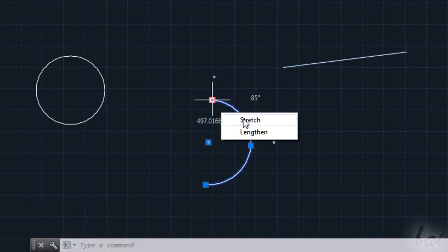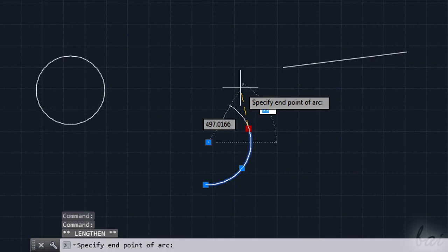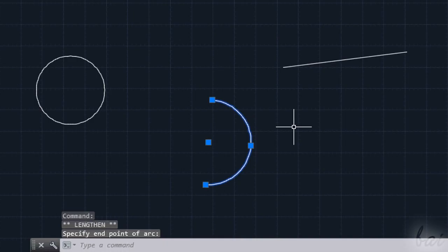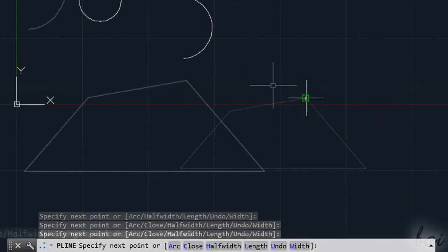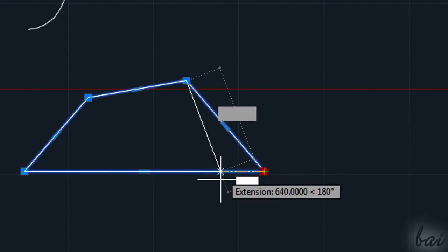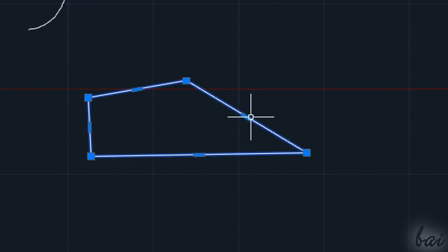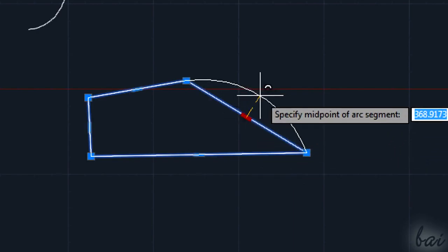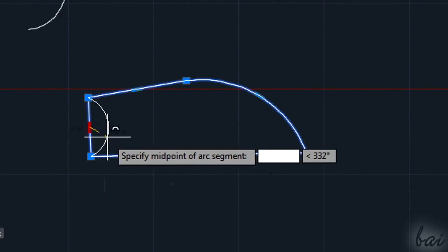Stretch lets you distort the object as you like, while Lengthen increases the length without changing anything else, like angles or scale ratio. In case of polyline or polygon objects, things are a little different. In this case, all the blue nodes are used to edit the object, including the ones that lay on the sides, for example to convert them to curves through Convert to Arc. In short, there aren't points to move them directly.